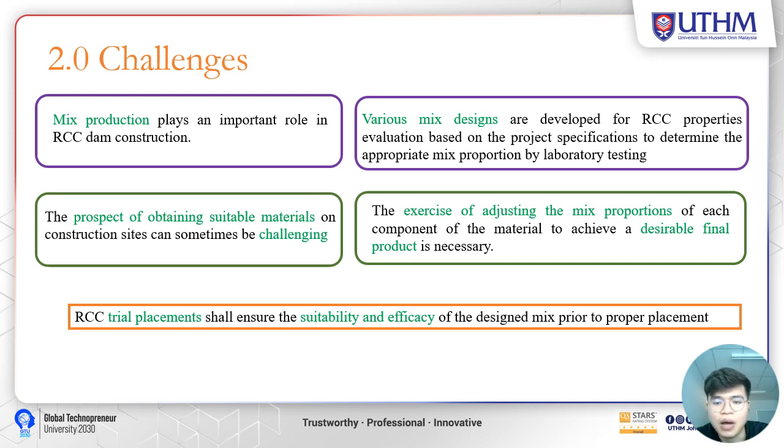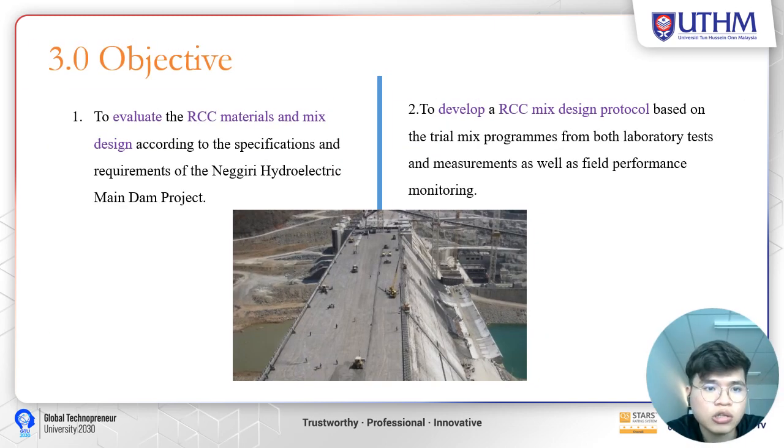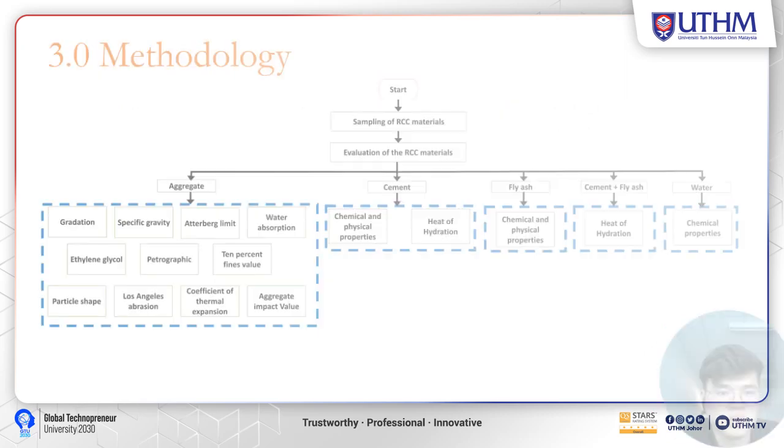And last but not least, the trial placement should be considered after all the mixed designs have been developed, to ensure the suitability and efficacy of the design mix prior to proper placement. The objective of this research is to evaluate the RCC material mix design and also to develop an RCC mix design protocol.